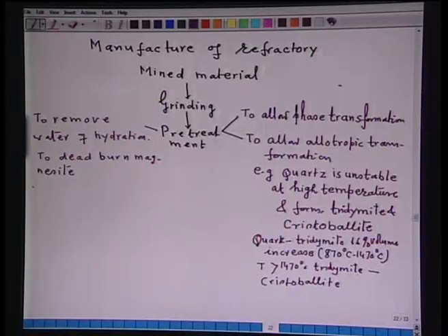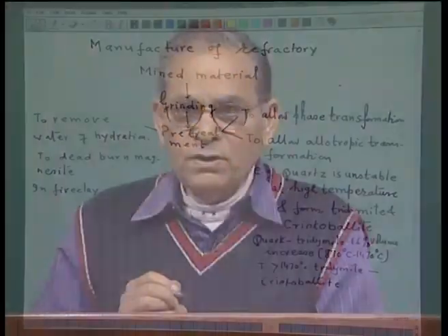Another important thing, in fireclay, is mullite formation, because mullite imparts resistance to slag as well as high temperature strength to the refractory material.